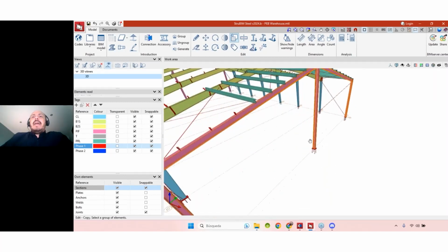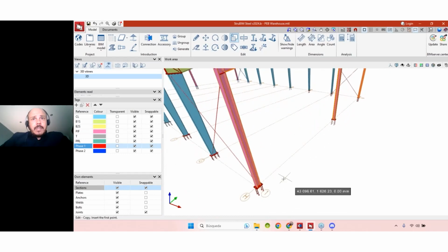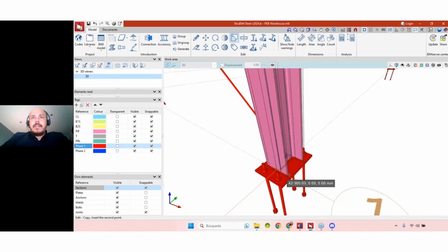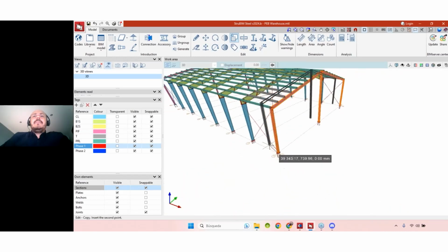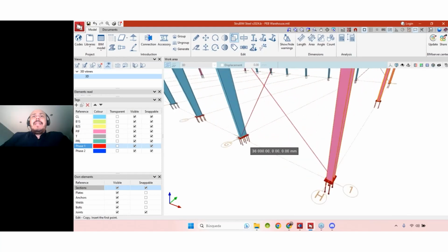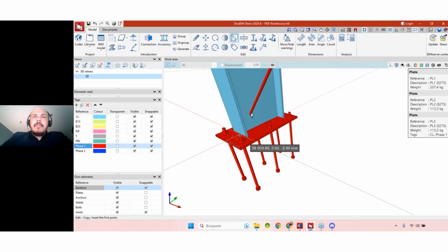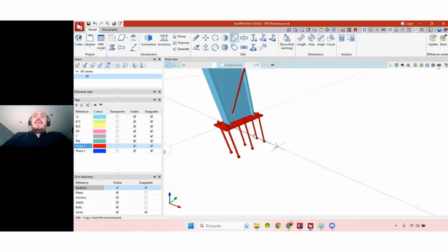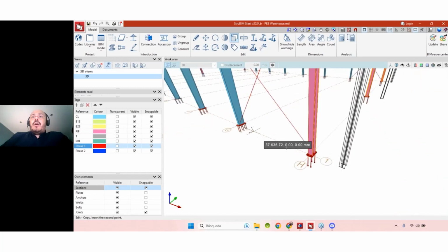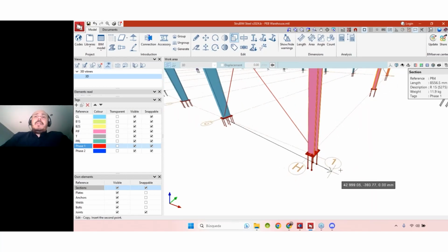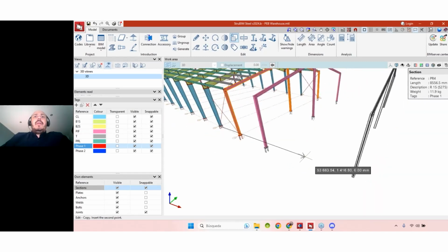Then we select the elements, we confirm with the right button of the mouse, and then we select a point that is going to be the reference to copy this element. For example, this point. Or I can select, to maintain the same distance, a point that is somewhere here. For example, I got the middle of this element. Now I can come to the other one here and put it here, at the same point. This was possible since the beginning. So we can easily do that.